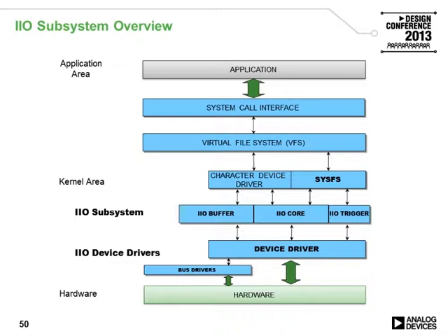In Linux, like in any other operating system, there is a separation between user space application code and kernel OS code. Applications all run in a private memory space and therefore are not allowed to call kernel functions directly. All interactions are done through system calls and the virtual file system. This block diagram shows where the IIO subsystem is located, how it interacts with the underlying device drivers, buses, and finally the hardware.